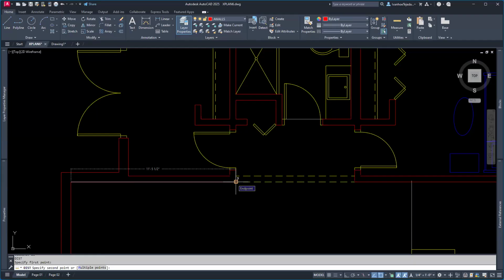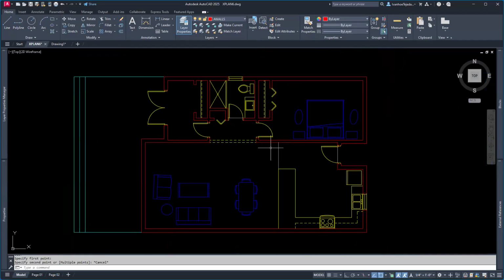So you always want to avoid those 1/2 and 1/4 inch dimensions inside and outside of your buildings. For the most part, on the outside, you want these to be whole numbers, whole feet. And if you're using inches, then round to the nearest full inch. And typically you want to round off to the nearest, let's say, even inch. So 2 or 4 or 6 or 8. But definitely, round off if you can, nearest foot. After that, to the nearest 1.5 feet, so nearest 6 inches. And then after that, you can use incremental inches, but keep them, for the most part, even numbers. All right, sorry to digress.